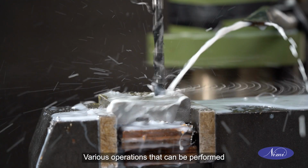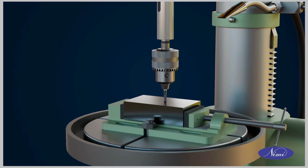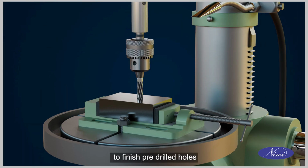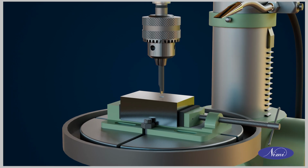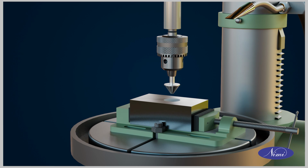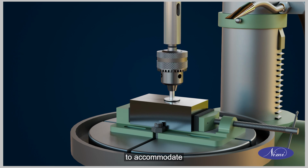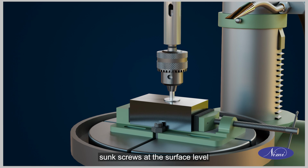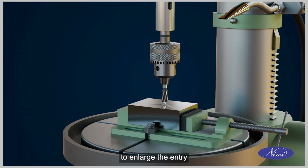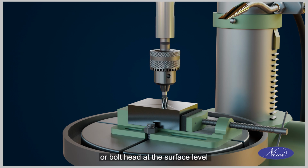Various operations that can be performed using a drilling machine are drilling, to drill holes, reaming, to finish pre-drilled holes, boring, to enlarge pre-drilled holes, countersinking, to produce conical shape at the entry of the hole to accommodate the head of countersunk screws at the surface level, counterboring, to enlarge the entry of the hole to accommodate the screw or bolt head at the surface level.